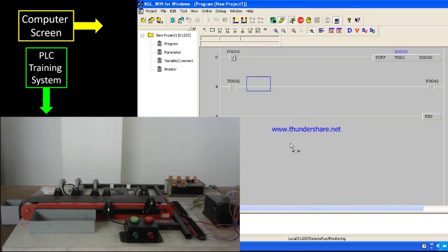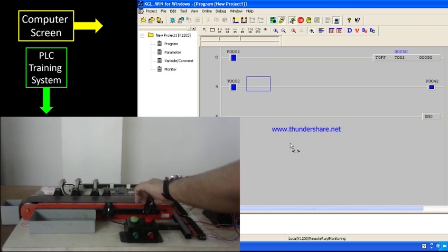So let's have this here. If I put my finger here, you can see that it starts at 50, where in case of timer on it starts at 0, counts up and goes to 50. But in case of timer off, it starts at 50 and it will count down and reach 0.